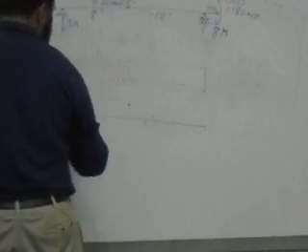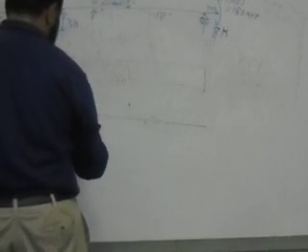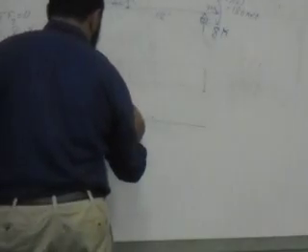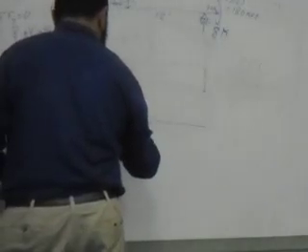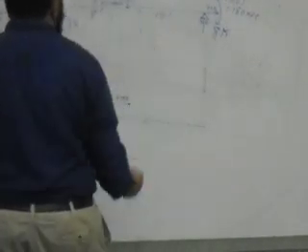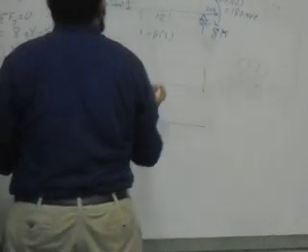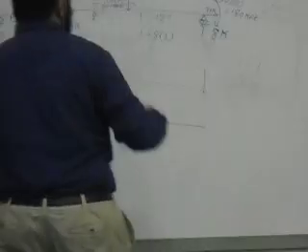What's the relationship here? Straight or curved or what? Straight line. That's a negative 24. But if I take a section just after B, what I'll have is the same negative 24, so negative 8 times 3, and something else which is more negative or positive.